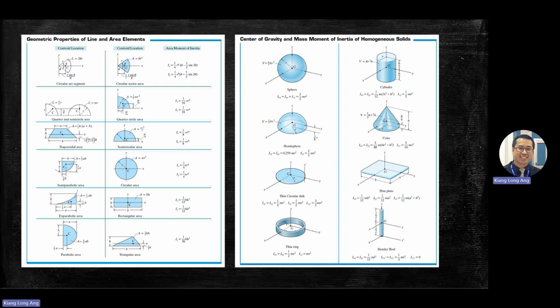So this one, I have I of the rod about O is IG plus MD squared. There's no D there. There's no D for the rod from here, from O. So IG, you read from the table. So you have IXX something. Then here, this also same. This is at the center, so you're reading this one from the center.